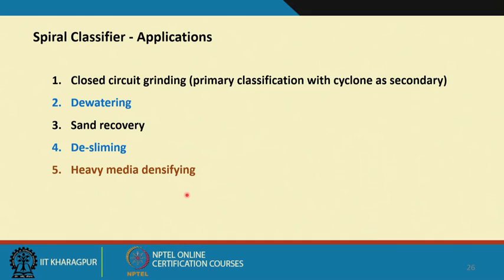You may have some very fine clay particles, maybe very fine coal particles, so you want to purify those, to improve the quality or grade of the magnetite. There we use it, because the ultrafine particles will be carried through the overflow water, and the magnetite particles, because of their higher density, will settle and be carried through the spirals.